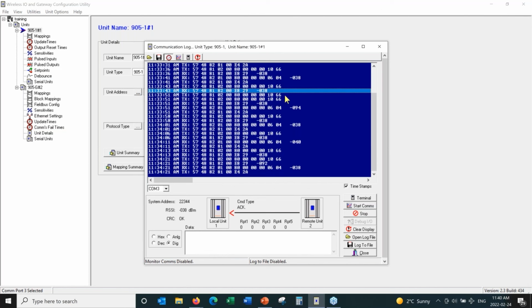Perfectly normal radio operation. All radios are designed for this type of thing. All radios do retries automatically exactly because of this type of communication. So for a radio system to be doing retries, it's perfectly normal to be doing 1 or 2 retries. But if it has to do all 5 retries, if you see the same line 5 times in a row, that means the message never got an acknowledgement from the remote site.